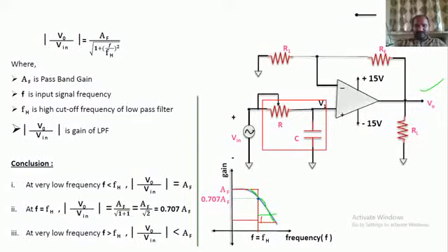Oh, sorry, wait a minute. Yeah, this one we are expecting. This is a first order filter. If you increase the order, it is going to be a little sharper one, which means only fewer frequency components are allowed by the low pass filter. We are not going to get the ideal characteristics anywhere, but we can reduce how many frequency components are accepted by the filter after the cutoff frequency by increasing the order of the system.